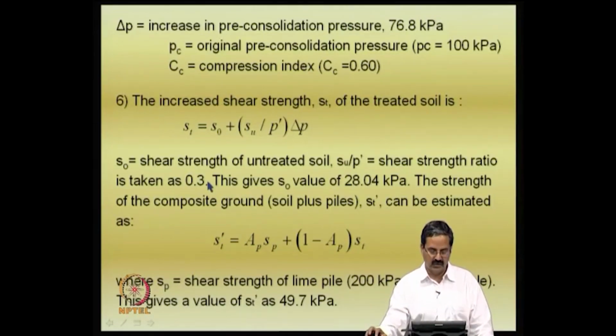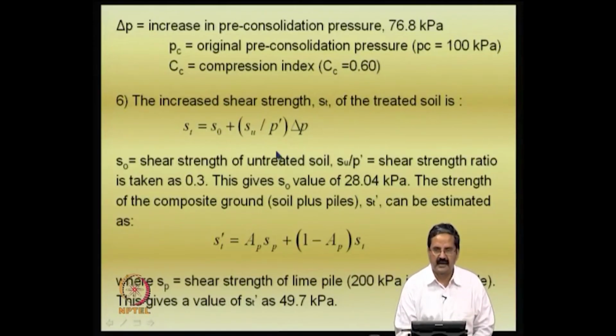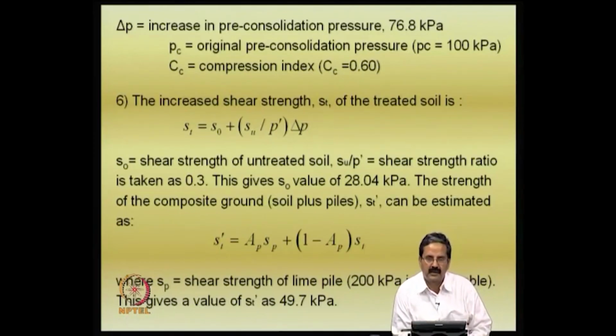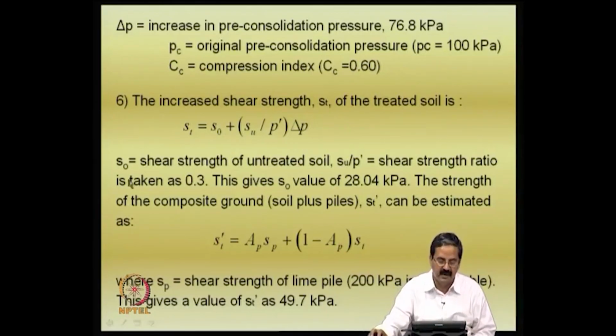Another one that I would like to show you is the increased strength of the soil, like initially there is some strength, and Su by P dash is another variable, which is actually established for many clays, and if you see in Bowles book also it is given, for various types of clays, like if you want to construct an embankment on a soft soil, how much load you should apply. You have what is called Su by P dash equations, say for example Su by P equal to 0.3 or 0.2 or something people say. It is there in literature, and in this case I have taken it as 0.3 actually.